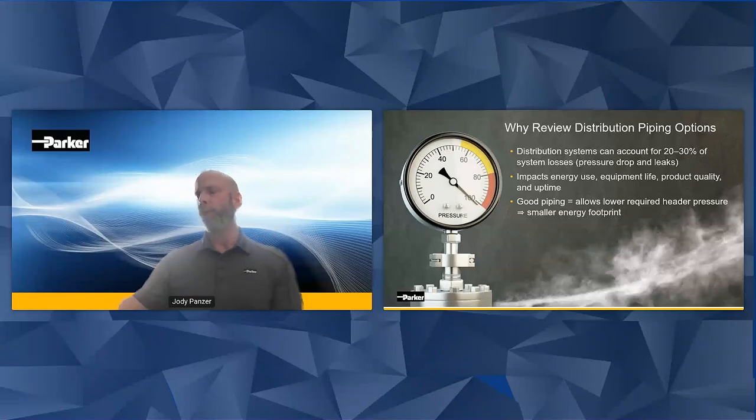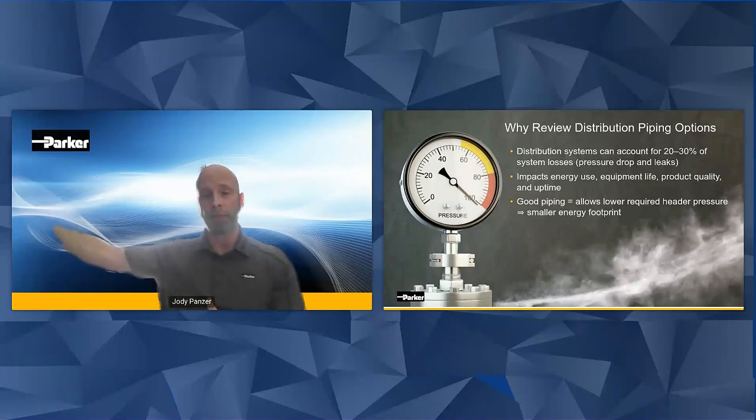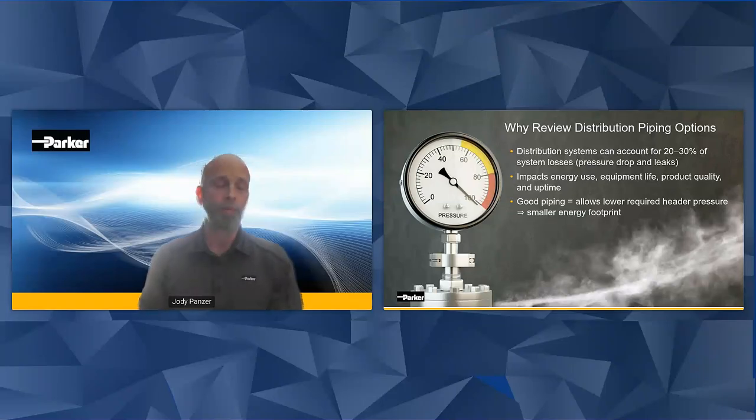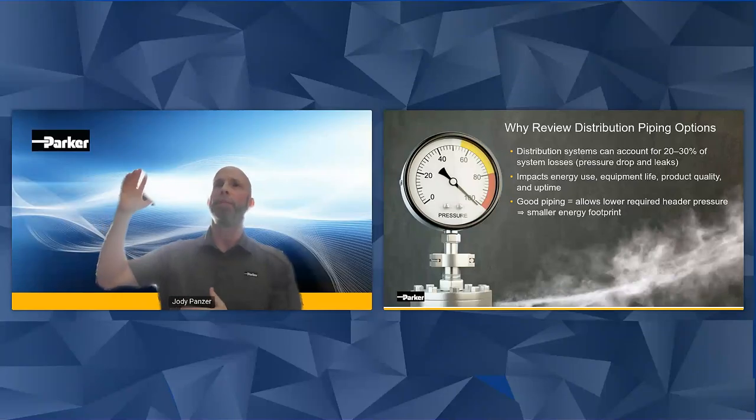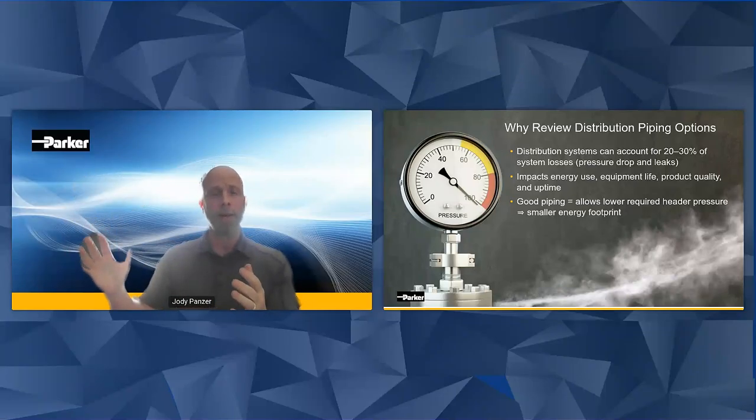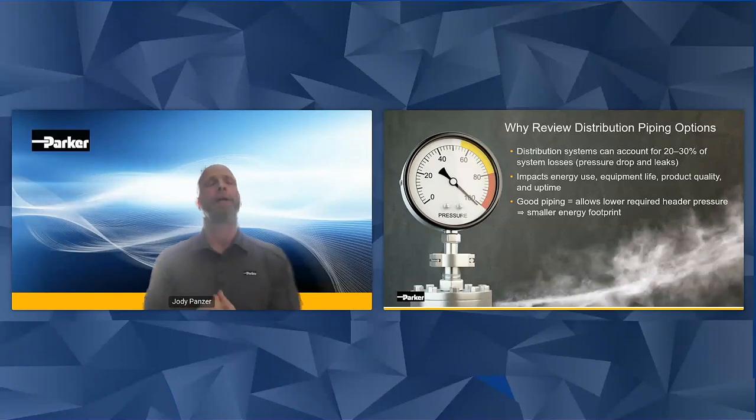Well, you may need 85 PSI at your equipment, your compressor's running at 95, and some of your equipment is starving for air or pressure. The typical thing that an operator will do is go to the compressor, see that it's at 100 PSI, and turn that internal controller up to 125, or maybe max pressure is 150 PSI. Not thinking about the piping that may be designed incorrectly, maybe it's undersized, maybe there's corrosion within it that is causing back pressure and making your compressors run harder to overcome that. But every 2 PSI we increase is going to cost 1% in energy costs.